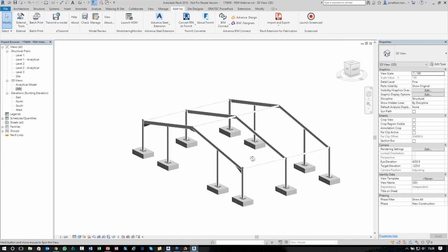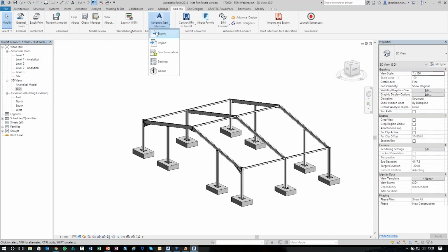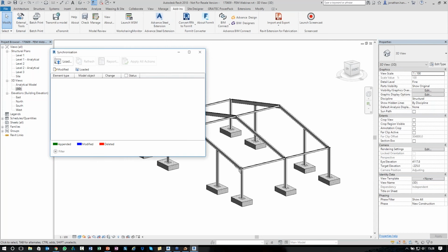Then click close, go back into Revit, and you can see that sometimes, depending on what way it's imported, Revit doesn't always update the graphics, but what I tend to do is just select all the instances visible in the project, right click, and I quickly go in and I start to play about with my visibility graphics. I tend to turn them solid, go to a surface transparency. So to do that, select this, visible in the view, override the graphics.